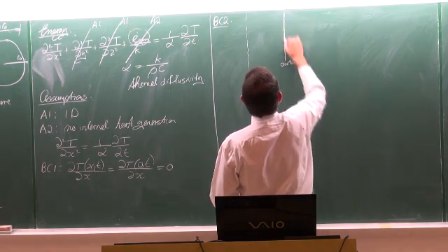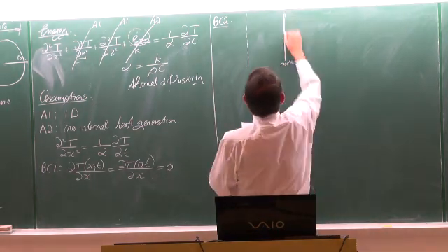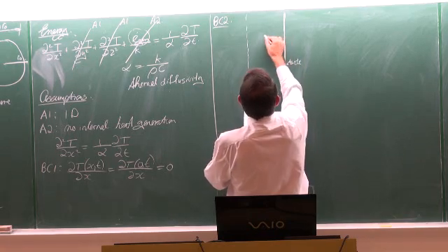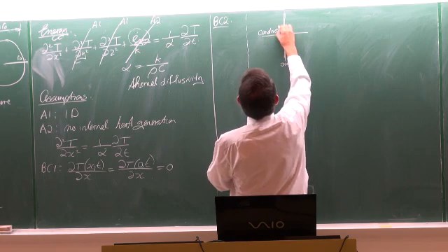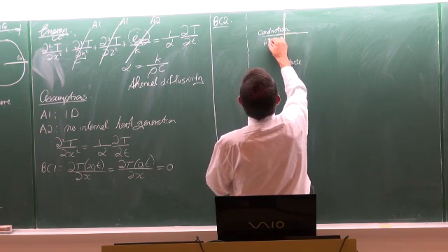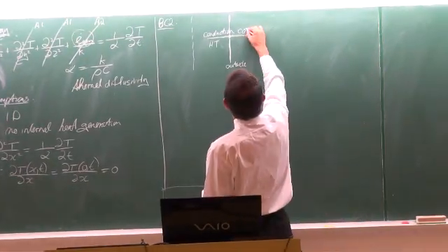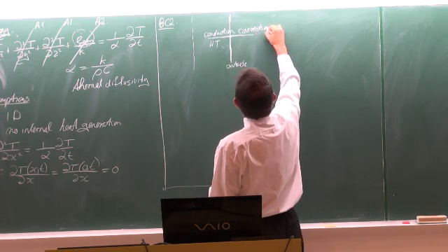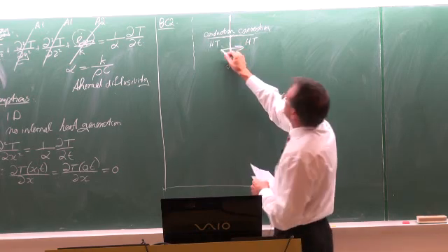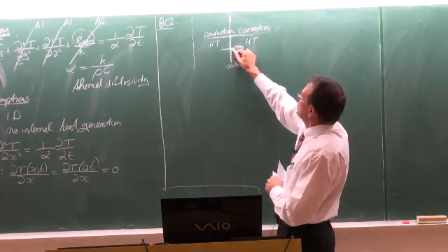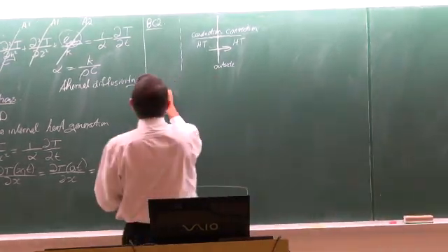This is now the wall of the large plane wall, or the surface. Then we can say that on the surface, the conduction heat transfer must be equal to the convection heat transfer. So if we look at the heat transfer going through the surface, then the conduction heat transfer there should be equal to the convection heat transfer. So that gives us our second boundary condition.